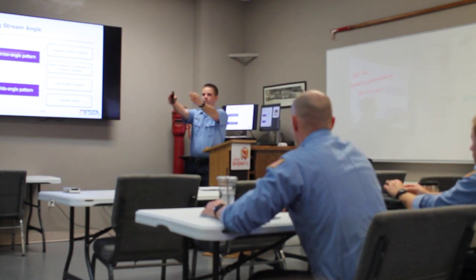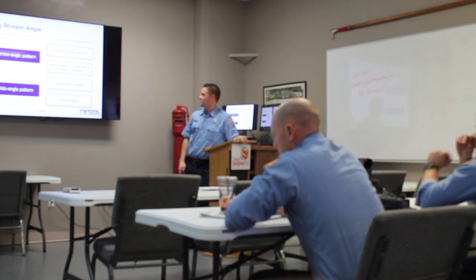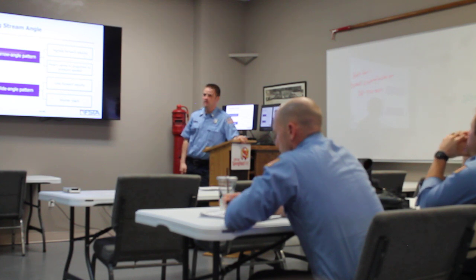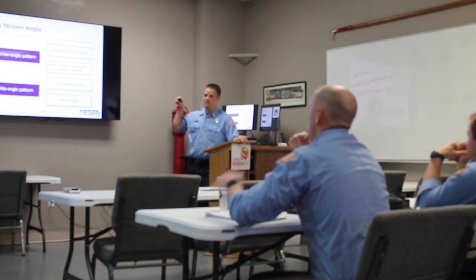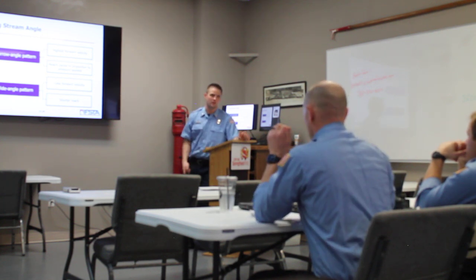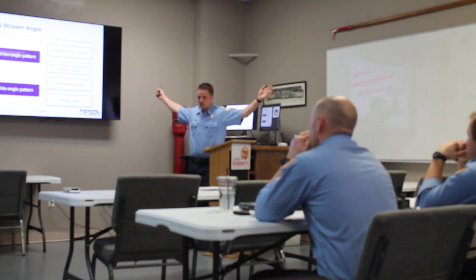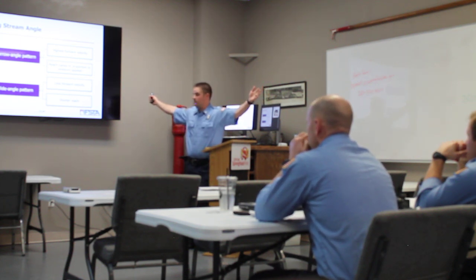Narrow angle pattern. It's the highest forward velocity. So it's more together, so it's going farther. Reach varies in proportion to the pressure applied. So that's going back to velocity coming out. How fast is it going when it leaves the nozzle, and that's going to be how far you're going. Wide angle pattern. If it's 90 degrees, it's not going to go very far.